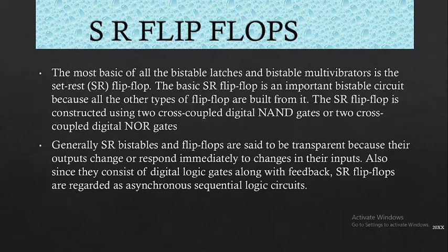The SR flip-flop is constructed using two cross-coupled digital NAND gates or two cross-coupled digital NOR gates. So SR flip-flop can be constructed by using NAND gates also and NOR gates also. This cross-coupled term, I will talk about later on in the video, but for now we need to understand that a flip-flop can be made by NAND gates also and NOR gates also, both ways.